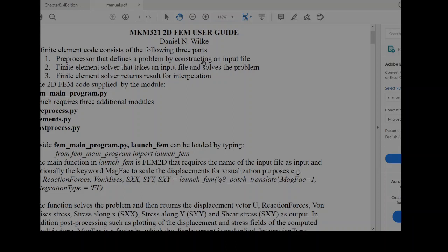As an engineer, that means you verify, you trust the numbers, they are what they should be, in the same ballpark. Or you validate your finite element, say this model is appropriate for what I want to try and achieve. It relates to reality. That is critical to understand. This interpretation is not just willy-nilly looking at figures and being happy about that. It's verification and validation. It's critical interpretation, critical thinking, and making sure that you trust the answers. Okay, that is critical. There's no two ways about that.